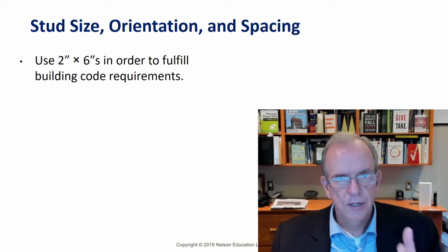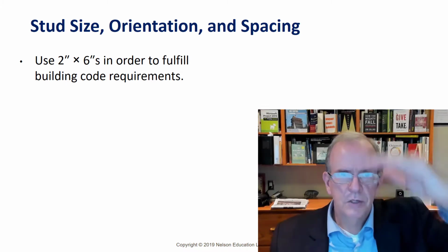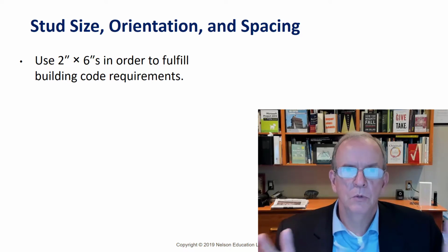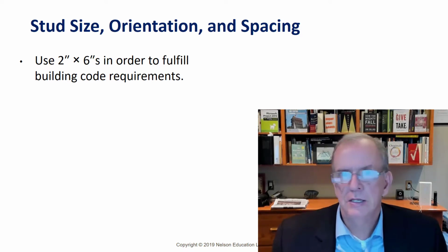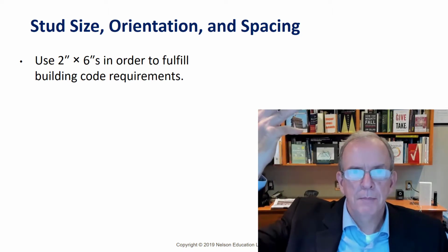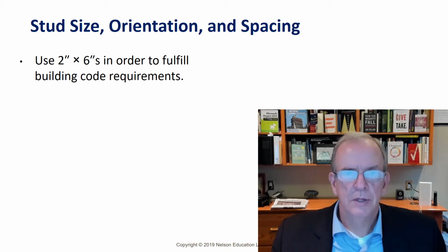That's one reason. The other is, what is the unsupported height and how many floors is it supporting, and that will help to determine what's acceptable for the spacing. So we may not be able to use 19.2 on an exterior wall depending on what it's supporting up above. We may have to go with 16 inches on center instead. So those are some of the design requirements and considerations that fall into studs and stud spacings.